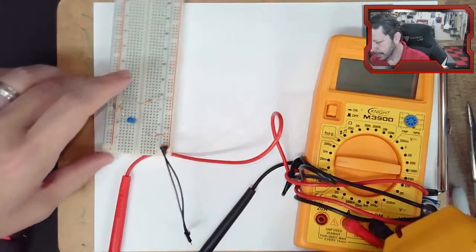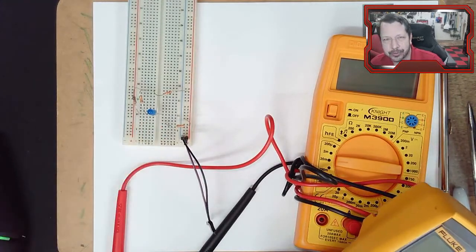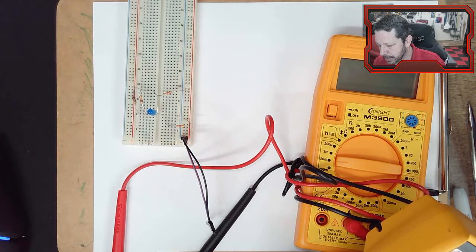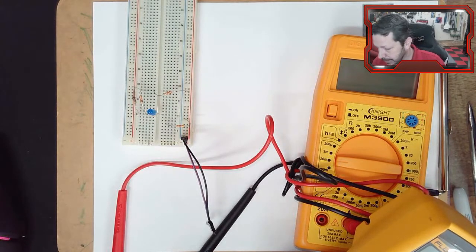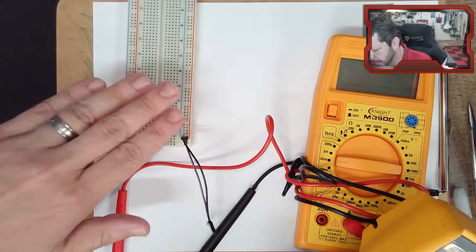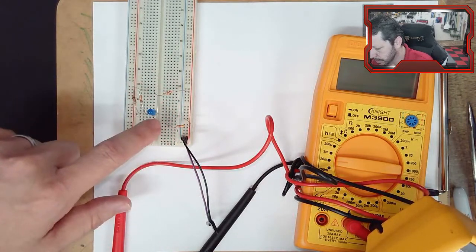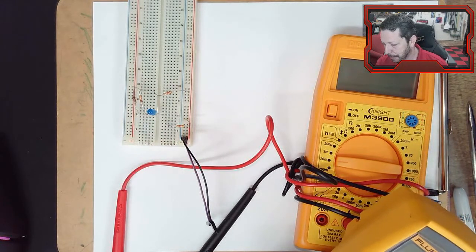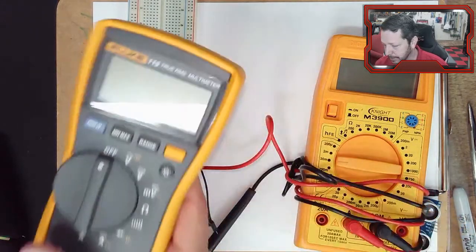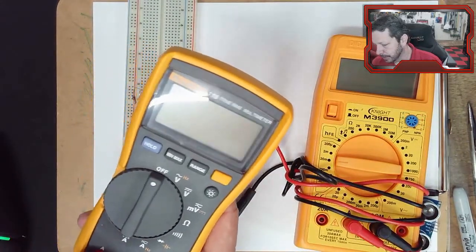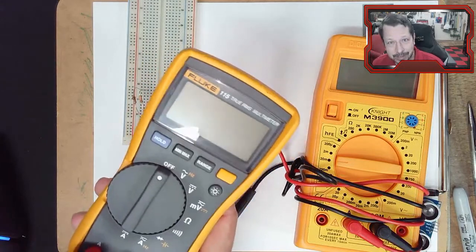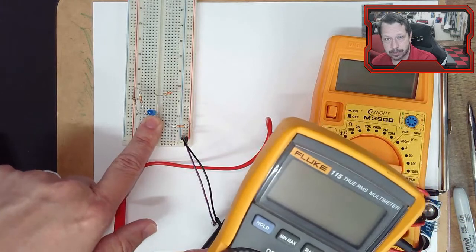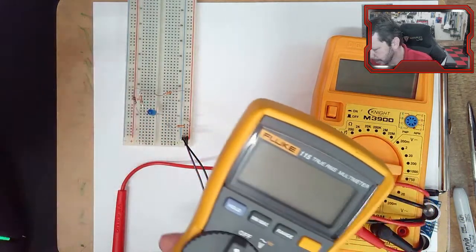Another problem was that I didn't have anything that was really drawing any current. I remember I said that we just made a little resistor network, and it was just a really, really bad heater is all it was. The resistance values we have here, like these are all 1,000 ohm resistors, I believe. So it was pretty high resistance, and it wasn't really drawing current that this multimeter would have been able to read very well anyway. It might have, but it would have been a very tiny current. So I've added the LED to have something to draw current. So we have to do a little bit of work now and light up an LED.